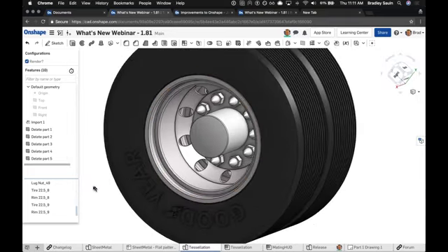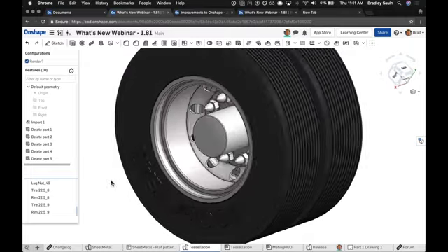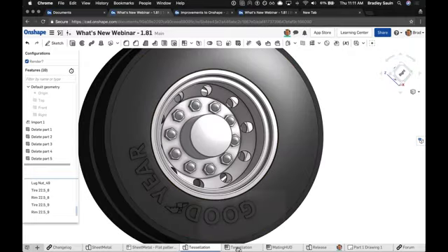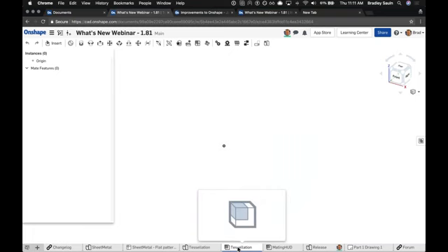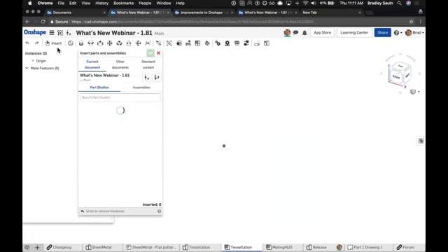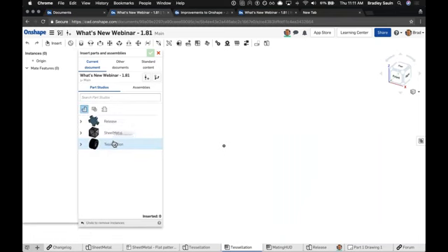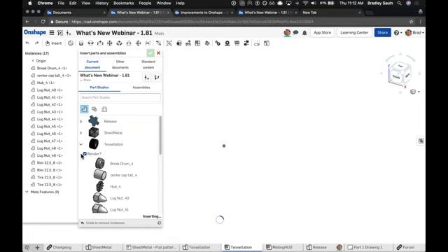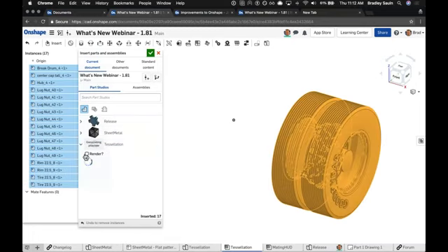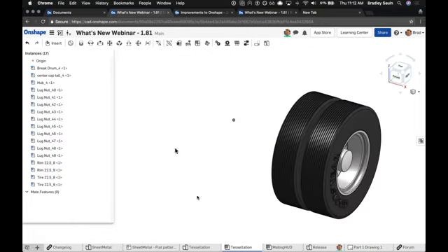And this does and will carry over into the assembly space as well. So if I now come into this assembly tab on the right, I can come in and actually insert that tessellation Part Studio of the tire that I was looking at. And of course, since I did set a configuration, I can choose whether I want this rendered or not. So that choice is entirely mine. I can come and actually insert those components.